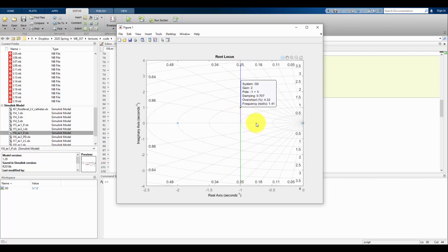So the trade-off, and this is what we saw when we were just testing different values, there's that inverse relationship between natural frequency and damping ratio, and that's why we saw for this plant, putting it into the control system, the P controller at least, that if we wanted a lower peak time, well, we had a higher max overshoot. If we want a lower max overshoot, we had to have a larger peak time. And possibly we want both to be smaller. But the problem we have right now from a graphical standpoint is ideally if we want both small, well, we can make the natural frequency larger but make the damping ratio remain the same if we were able to choose points over in this region.